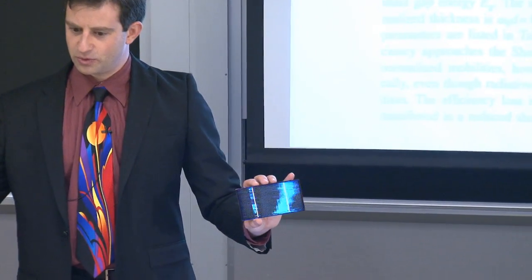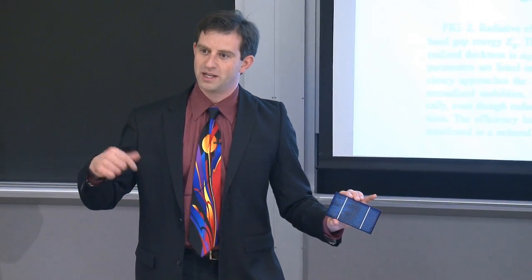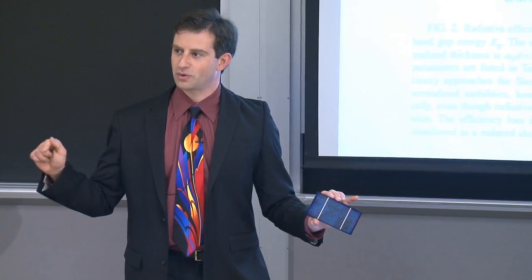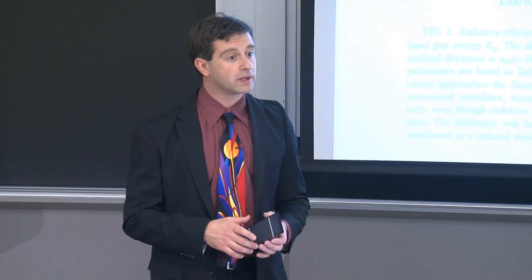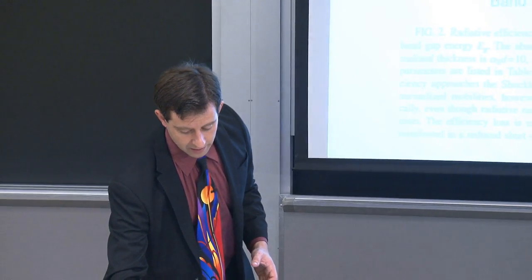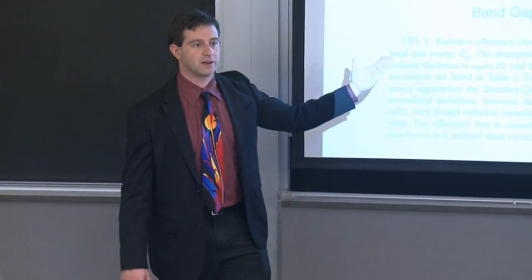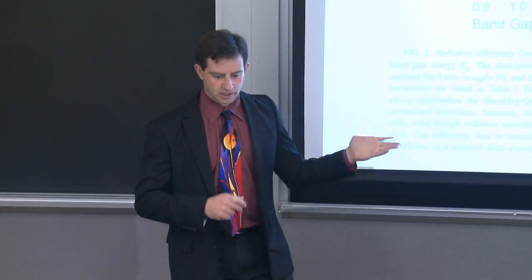Now you compare to amorphous silicon, which has something in the range of 10 to the minus 3 to 10 to the minus 1 centimeters squared per volt second. And you can begin to see why those materials with poor mobilities are really impacted in terms of their performance. There is a method to calculate the impact of limited mobility on device performance. And if that intrigues you, I would definitely refer you to this manuscript.